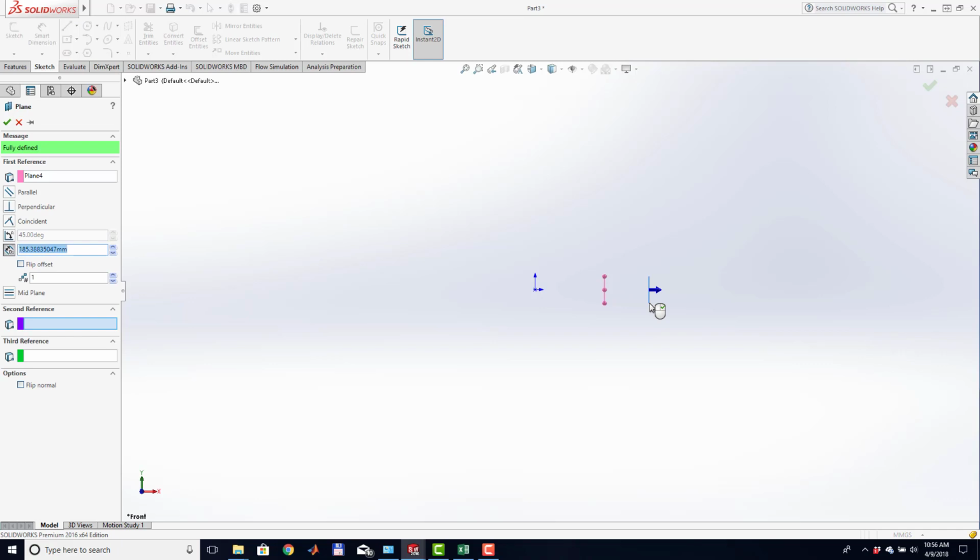And we can save some time by adding 4 reference geometries at the same time if they happen to be at the same spacing difference. I believe we have 144.8 millimeters, and I'm reading this off of the spreadsheet, and I'm going to put 4, and there we go.